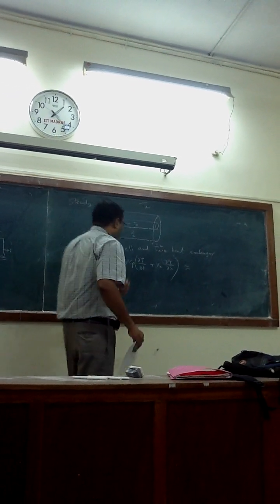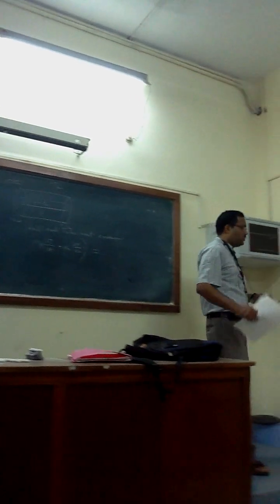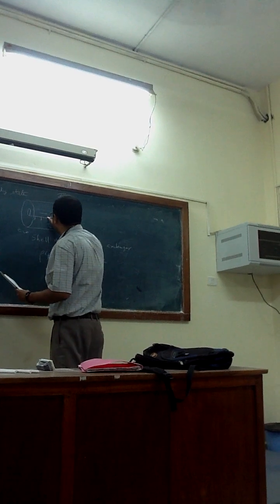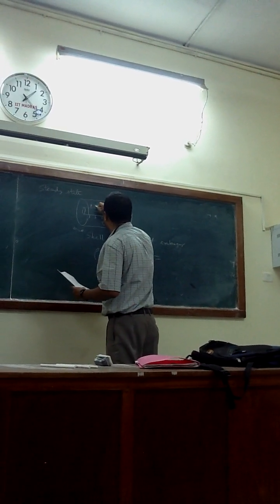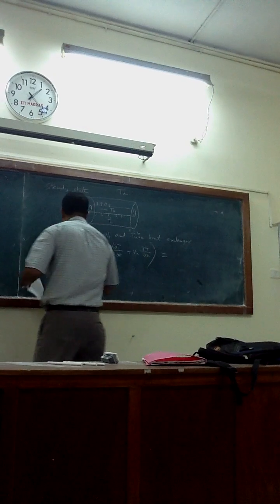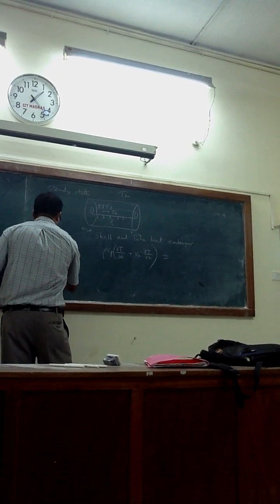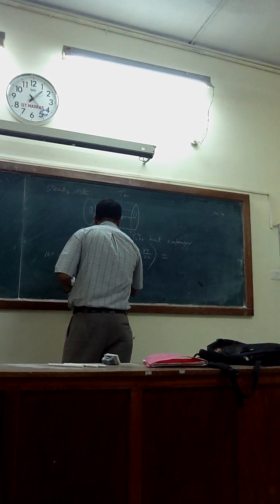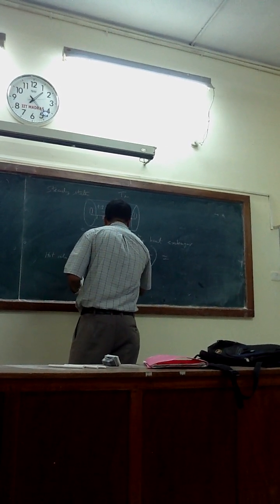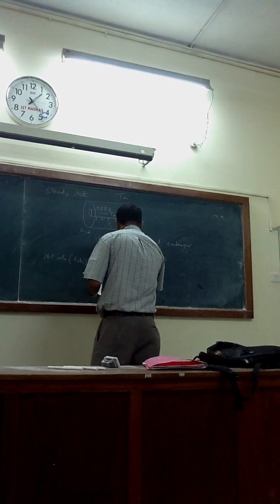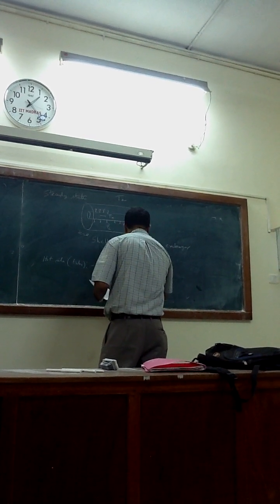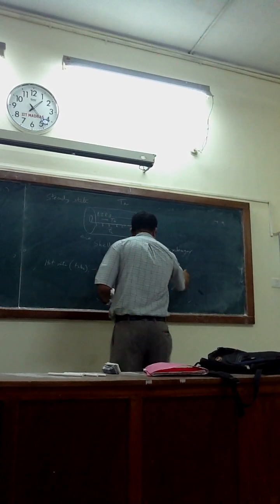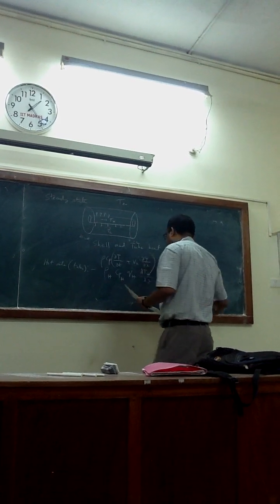And then the rate of heat generation and destruction, it will be lost from the wall. So volumetrically it will be lost. So what will be my equation? My equation for the hot side or hot tube will be rho of hot fluid, Cp of hot fluid, QH, dTH/dz equals minus UP (TH minus TC).